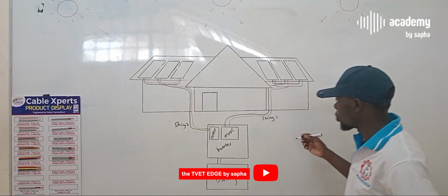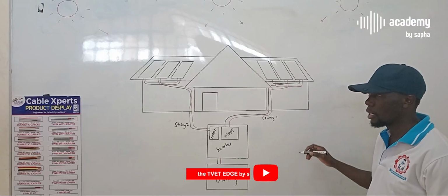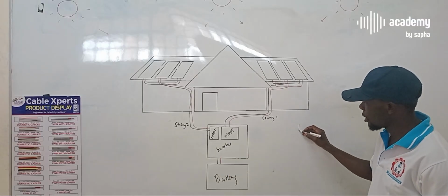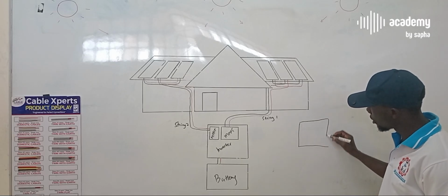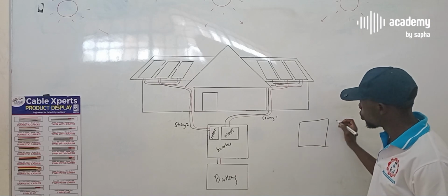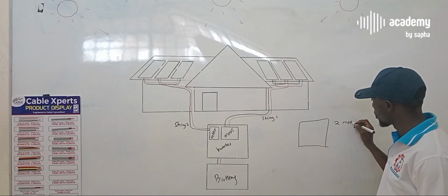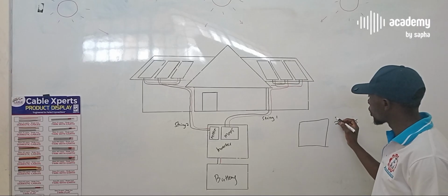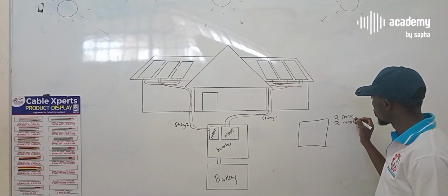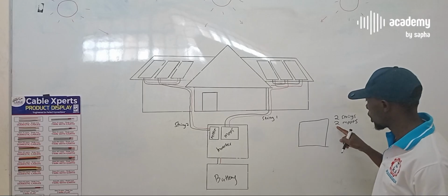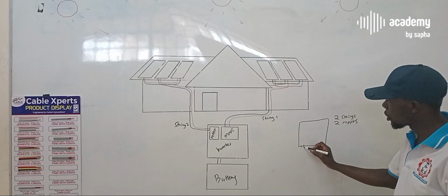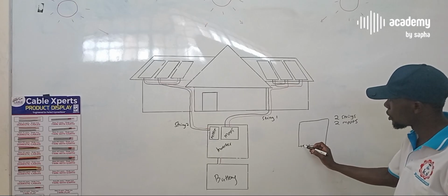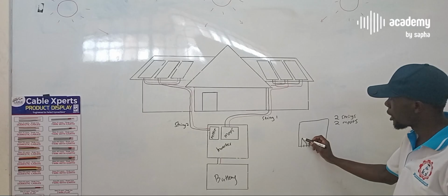The specifications said that the inverter had two MPPTs and could accommodate two strings independently, with two MPPT charge controllers. But when we opened the inverter, we realized that both strings were in parallel and ended up in one MPPT.